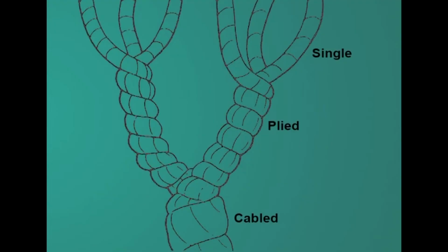And if the yarn twist is very high, up to a certain level the yarn twist leads to strength in the yarn, but later at a point we can see that the strength starts decreasing after the optimum point. In case the yarn twist is very hard, we get a very hard yarn, the diameter of the yarn would become thinner, thereby the covering factor would come down, and sometimes there are some kinks that evolve out of this yarn, and it is most suitable for crepe fabrics. So, we see that we can use a single yarn or a plied yarn or a cabled yarn.